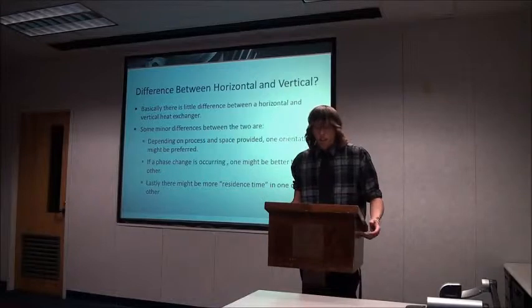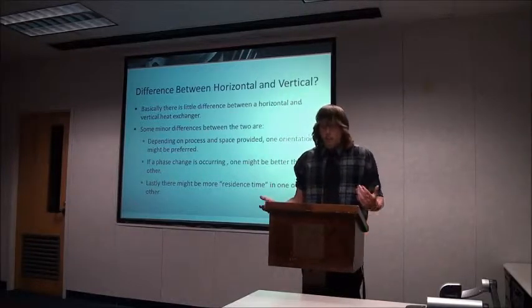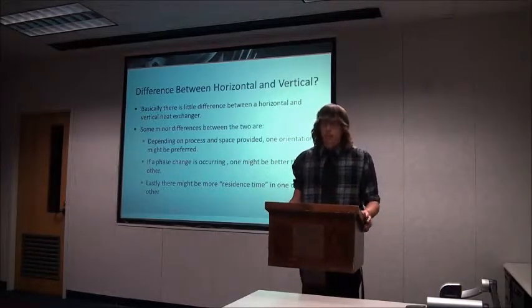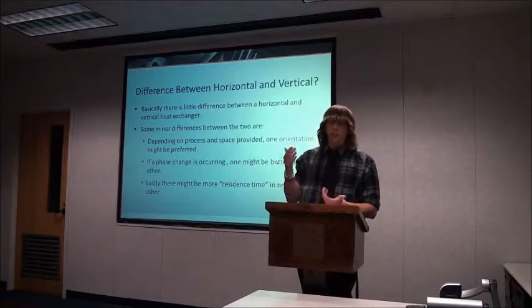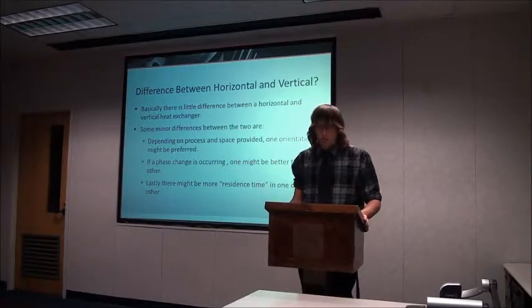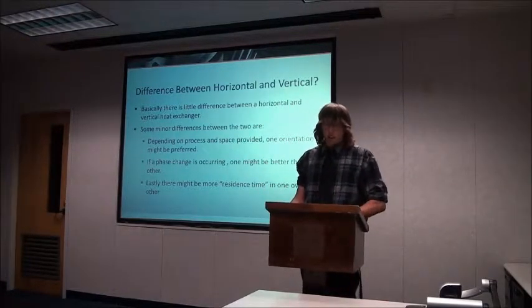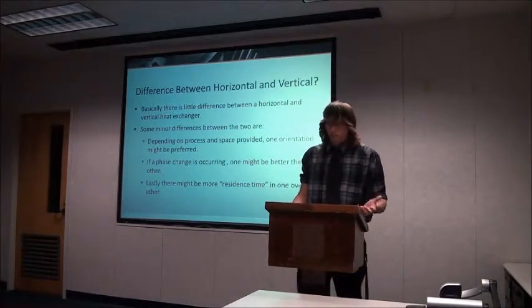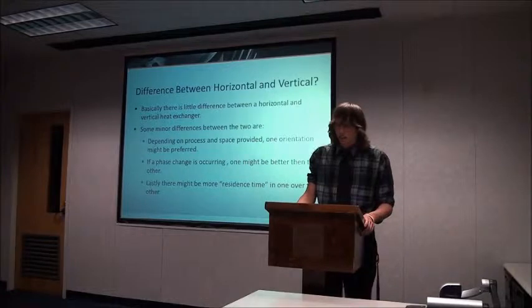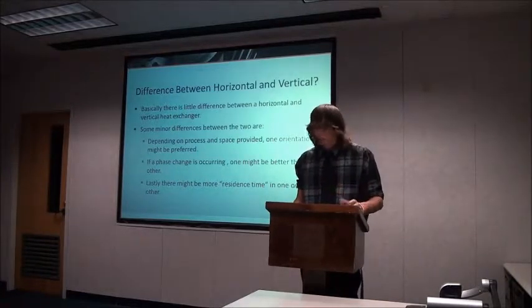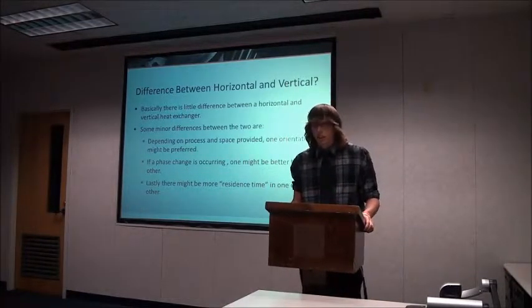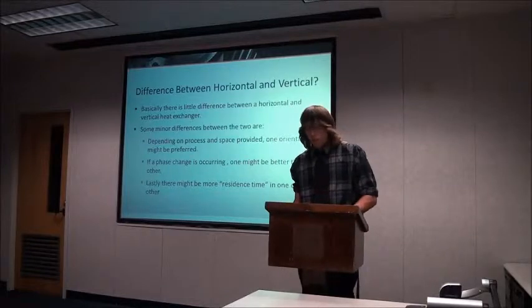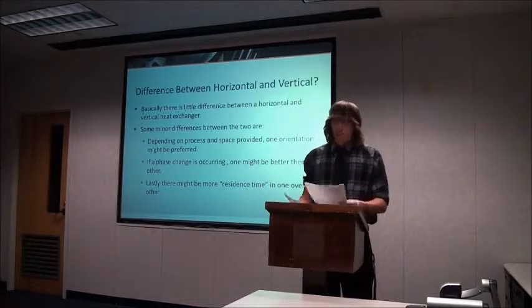For the phase changes occurring, one might be better than the other. In a vertical one, the gas would be less dense than air, so it might rise and be easier for it to get out of the vessel. And lastly, the horizontal heat exchanger might have a higher residence time than a vertical heat exchanger, and this can be due to the orientation of it also.